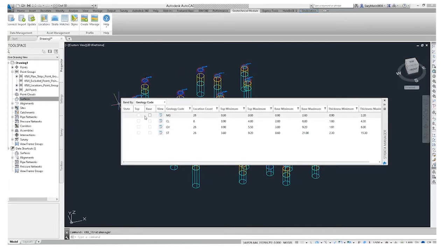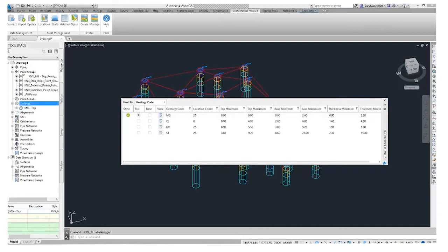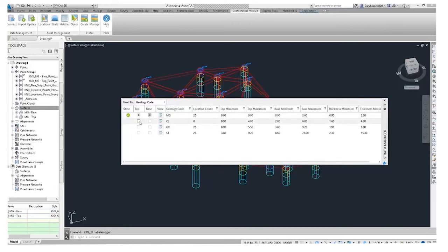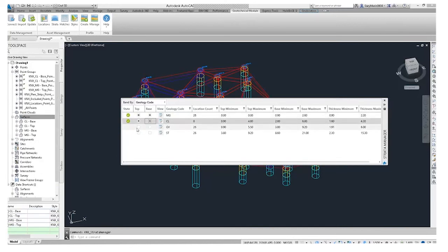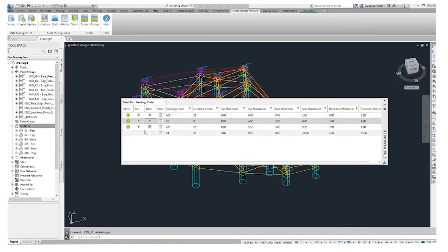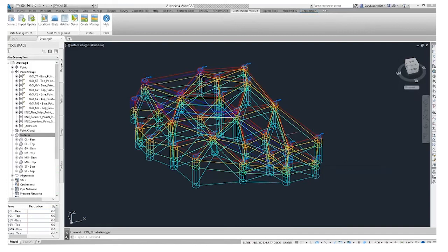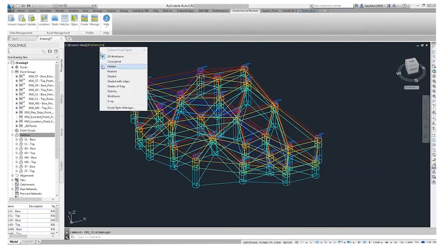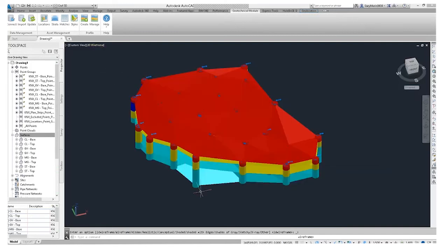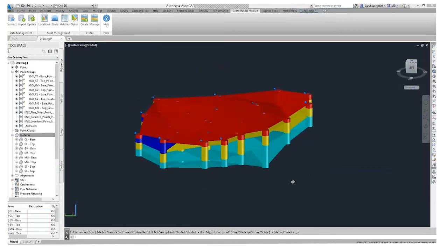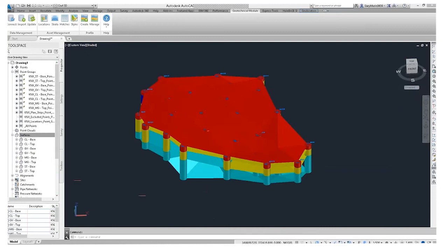Now, all we have to do is click. So for Made Ground top, if I click, it's created me the Civil 3D surface, and it's pulled in all the data for me. By just clicking, for each one of these, it's actually going in, creating the surface, and pulling the information in for me. So in a matter of a few seconds, and let me take this back into shaded view again, we have our geology being pulled in and displayed, and all of the Civil 3D surfaces are created for us.